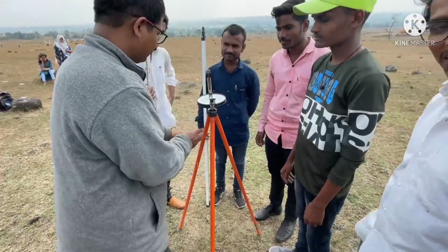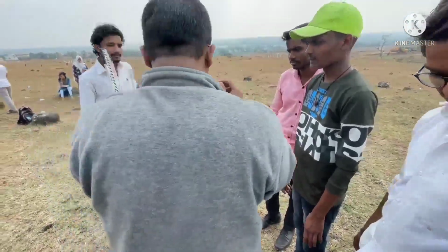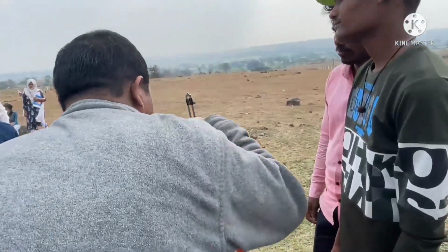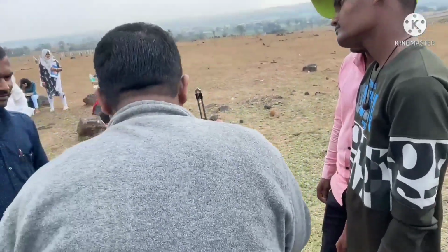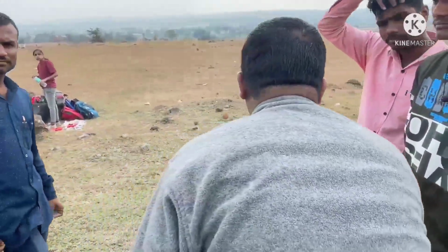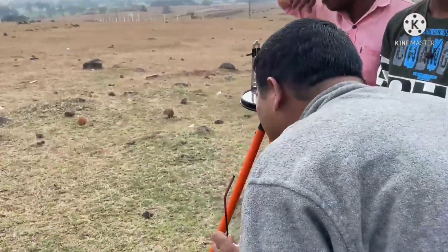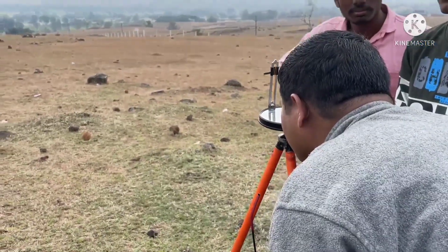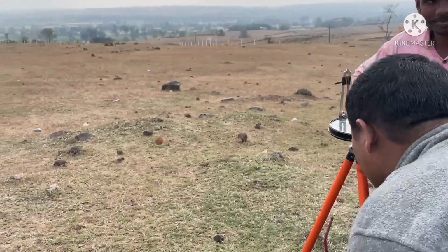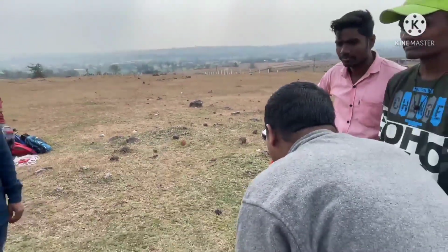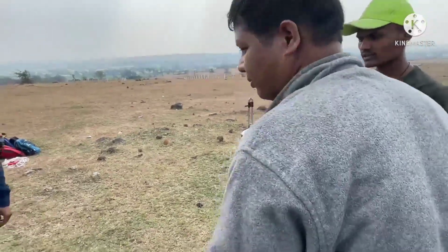When it is exactly over that C0, we are going to bisect the C100, that is the ranging rod which is placed at C100, through the eyepiece, and whatever reading we see there, we are going to note it down, and correspondingly draw the sketch in the final drawing sheet representing it.